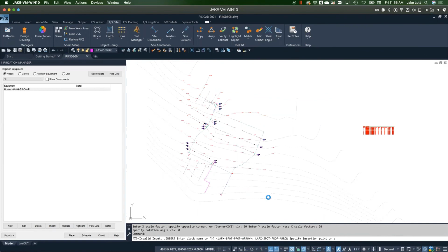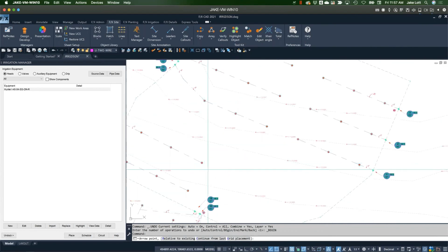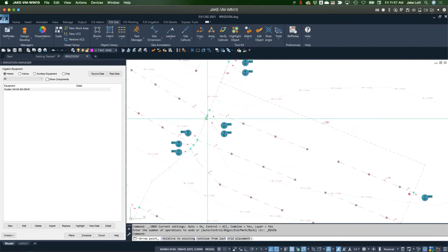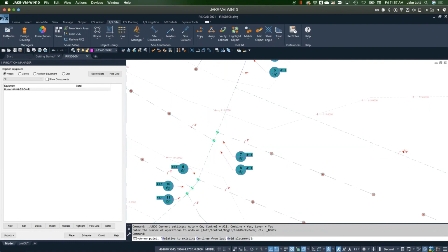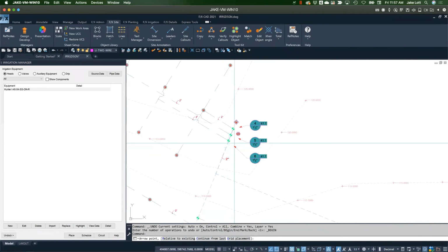Appropriate being what it finds that elevation to be. So if they enter that elevation in wrong, then we have a problem. But you can see that pretty easily in what I'm going to show you. What's nice is it just placed all those for us very quickly. But for irrigation, we definitely want to be somewhat liberal with where we place them, because the system is going to start looking at the valve and where its closest spot elevation is.